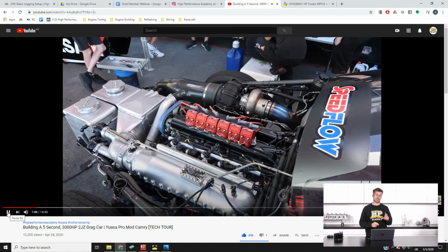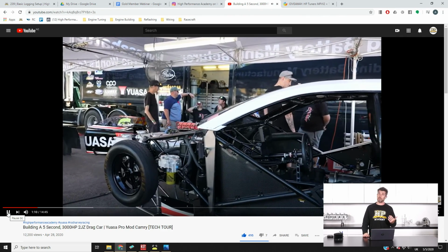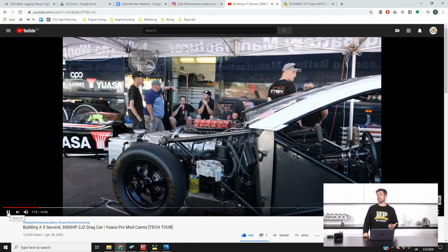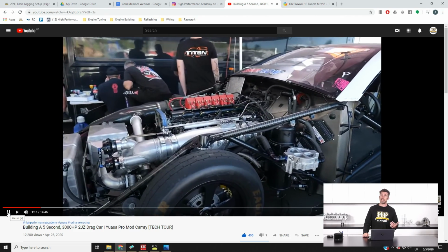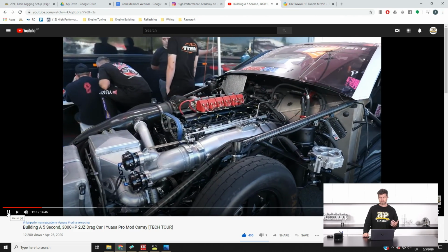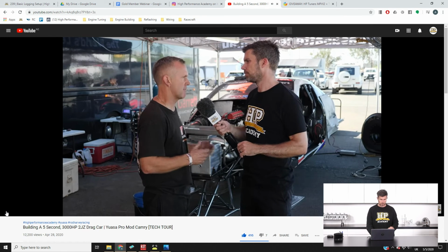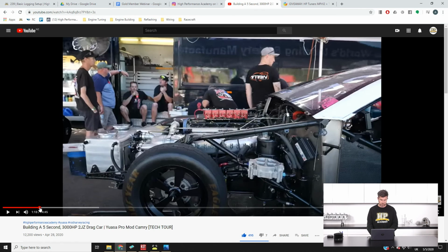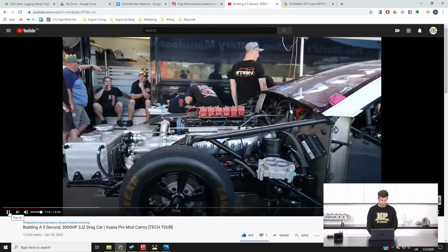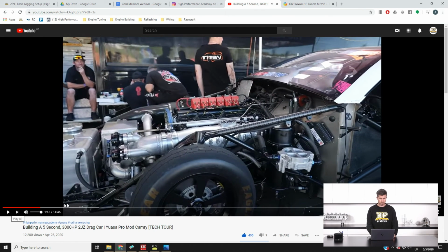One of the particular things we focus on the side of this video, which I found really interesting, is that the car doesn't actually run a wastegate at all. Instead, it uses a drive-by-wire throttle body that's mounted off the intercooler. In fact, I'll just dive back here because it is pretty cool. I think we can just see it here. Yeah, we'll just pause here.